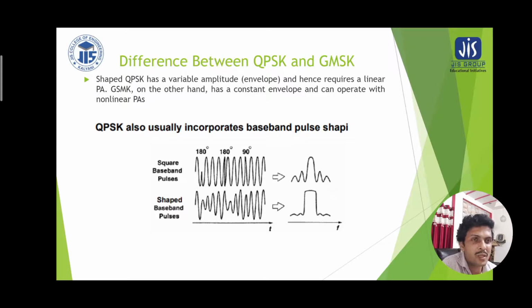So once we suppress the side lobe, there is a suppression of the message. So such non-offset QPSK is not a wise solution. So that is why offset QPSK has been taken.